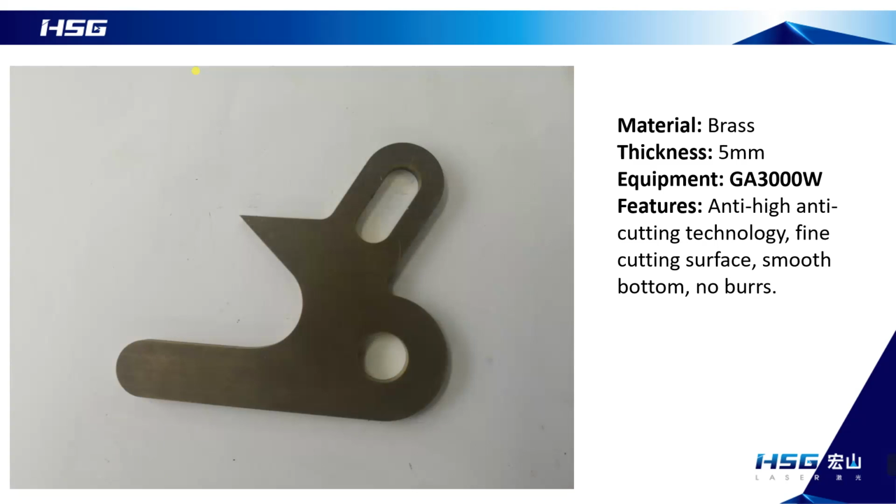Because brass, copper, and aluminum plates, they're all highly reflective material. If the laser power control is not good, or the cutting process is not good, it is likely to lead to an alarm, and even lead to a permanent damage to the laser. So that is anti-high reflective technology.